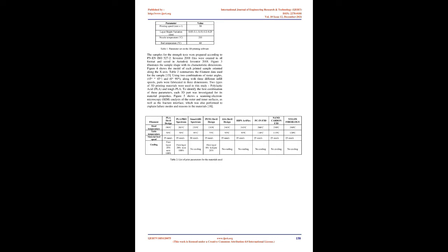The concentric pattern yields the most desirable tensile, impact, and flexural strength due to the alignment of deposited rasters and better consolidation of layers with the loading direction. The pressure and temperature of the autoclave have a positive effect on the PLA samples, which help them to reorganize the structure, hence strength properties were enhanced. The test results were also compared with injection molded samples for better understanding 17.